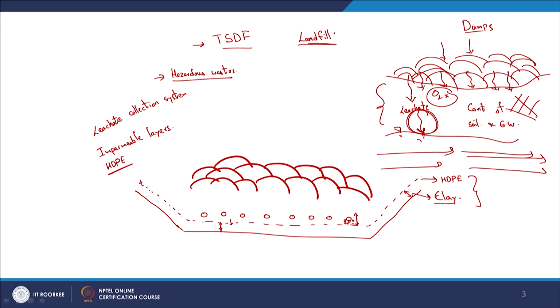Obviously, what will this particular leachate collection system have? It will have perforated pipes through which the leachate is collected and pumped out. We will look at a few pictures, and we will also have a geotextile layer, not membrane, wrapped around these pipes, and up above and beneath we are going to have relatively more pervious types of materials, gravel, sand or such, depending upon the site obviously, right.